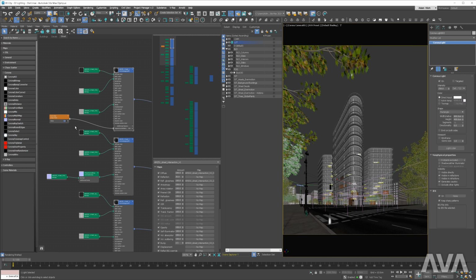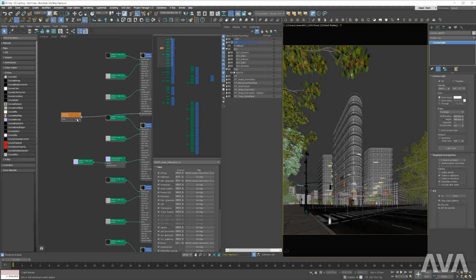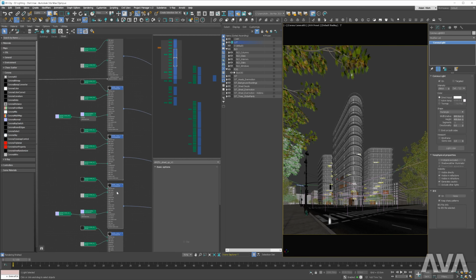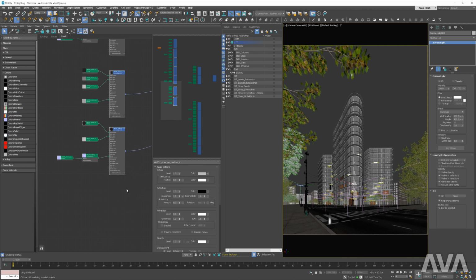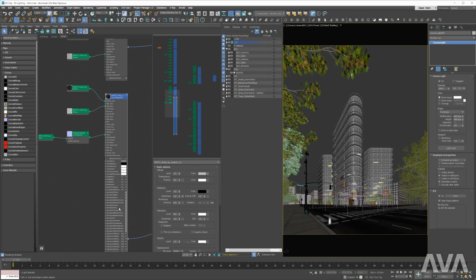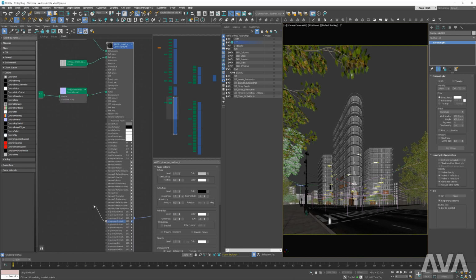Now you can see that when I change the value here, the value in the Maps tab is changing as well. Thanks to this technique, by changing the controller value, we can control the value for all the materials we choose at once. To make the process faster, select All Materials, then right-click and choose Show All Additional Parameters. Choose the correct parameter and plug it into the controller.